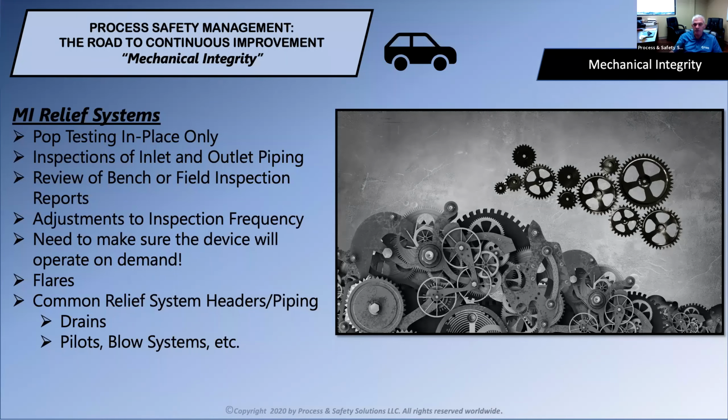A lot of times in an industry, if you see a lot of smoke coming out of a flare, you know you probably have issues with steam, and smoking flares normally are a direct result of not enough steam for those particular items. Not always, but most times.